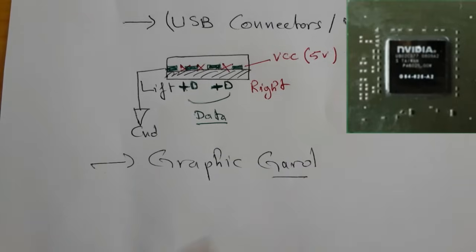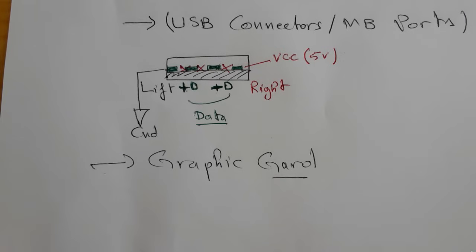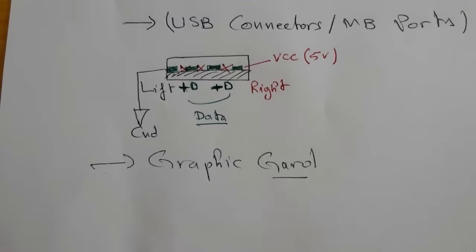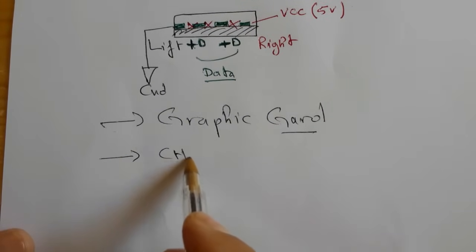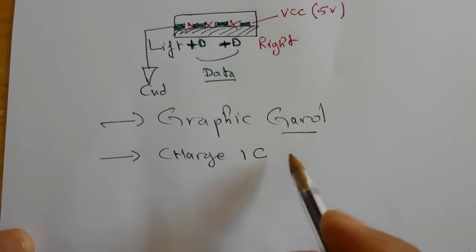Of course, this is a very common fault. The graphic card is a very common fault that causes the problem of no data on the screen. If you have a bad graphic card, you can get a black screen, no data. That's why there are many techniques to repair the graphic card, such as overheating the chip using the hot air gun.